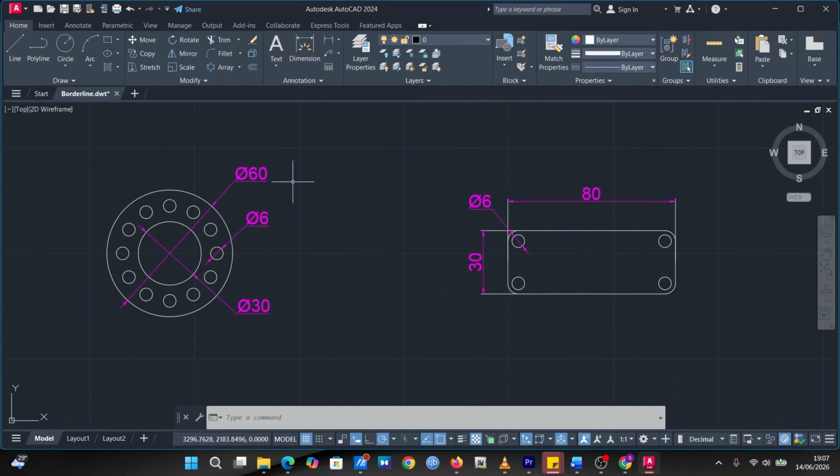That's what I mean. So we have to take this out so that if we transfer it onto our drawing sheet, we are no more going to see these boxes in the background. To take the grid off, you come down here, you see model here, then you see this icon over here, display drawing grid on, then you just click on it. Now you can see the background is empty and it's just left with our drawing.